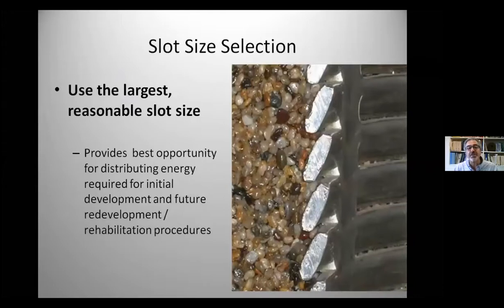Final word about slot size. Again, what I try to urge people to think is, don't look at the slot size as the last hope for controlling sand. That's not the job of the screen slot. It's there to stabilize the filter pack you've just put in.